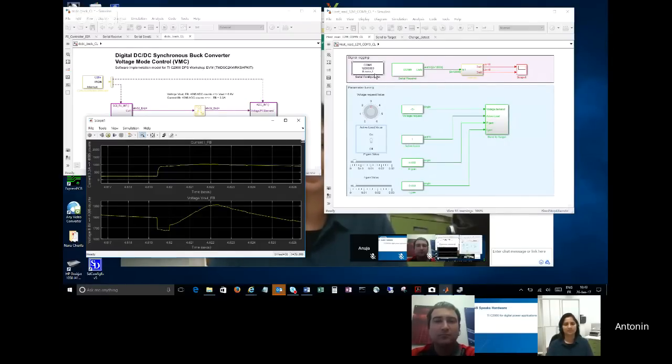Now, one thing worth mentioning, the algorithm runs at 200 kilohertz, and I'm sending 2 data points, 2 UINT16s, every 200 kilohertz, so that's 5 microseconds. So if you do the math, that's about 8 megabits per second worth of data that's going through that 12 Mbps connection. So I'm using quite a bit of this serial connection. Now this serial connection block, is it available out of the box, or do you probably share these demo files?